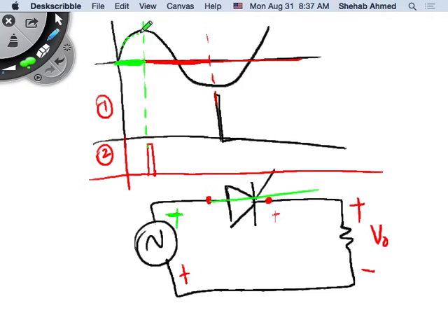I'm putting some positive voltage on this side and negative voltage on this side, right? So there's more positive voltage here than here. So I've created the condition, and I have an impedance, and this looks like a short circuit. So I have all the conditions for the current to flow. So current will flow, ID will flow positively through the diode, right? So this behaves like a short circuit because it's an ideal switch. So the output voltage will jump here, follow the input voltage, right? So I have the input voltage put across my output load, right?